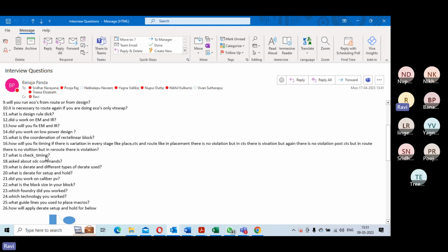Also for the inputs, you can give set max fanout. Okay. And you can give other constraints so that it doesn't duplicate that net. You can define the constraint such that the ports do not get cloned. You can do that also. But for SDC, I will not give you advanced ones. But these are constraints that you can specify.